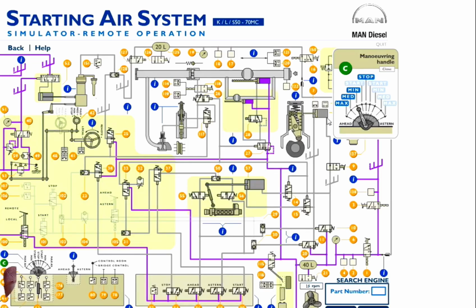Okay, let's give to medium. Okay, now the governor gives more fuel, and let's give to maximum, and let's give to stop to see what is going on. Okay, a signal stop here is going from this valve, air valve, here, then splits, go to fuel punctures, close to air distributor, and go to the puncture valve to the fuel pump to cut the fuel. Okay, so our engine is stopped.